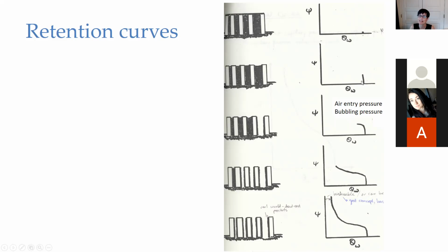This bends in just ever so slightly. So the pressure declined, and there's a little less water in our system. If you keep pulling, these big ones are the ones that break first. The smaller capillary tubes can pull water up higher, which means they can survive more tension. So these wider ones empty out first, and you start to lose water from the biggest pores.